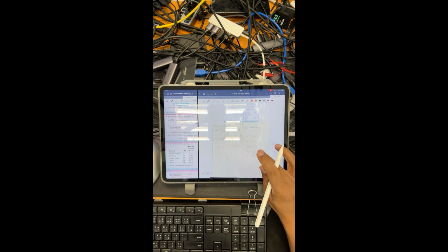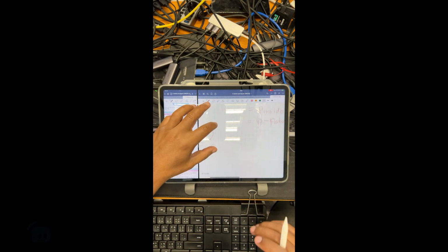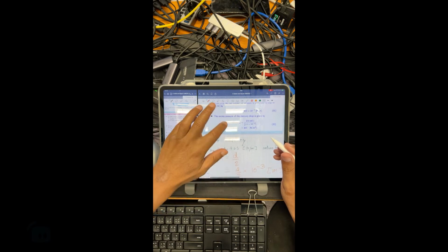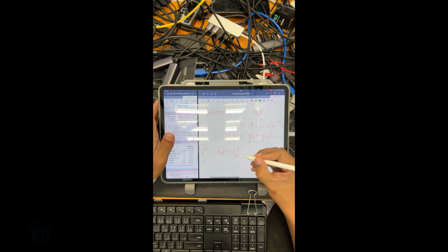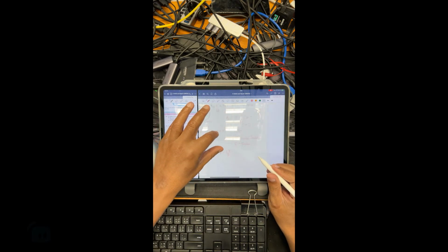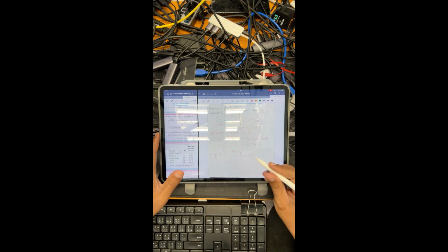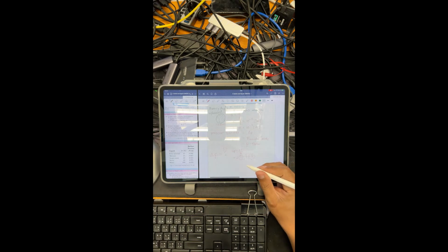So we are going to use formula number 30. Delta P equals 2 gamma by R. Gamma is what we got before, 0.465, by, oh sorry, I forgot the number 2, so 2 times 0.465, divided by the radius, which is 2 times 10 to the negative 3.